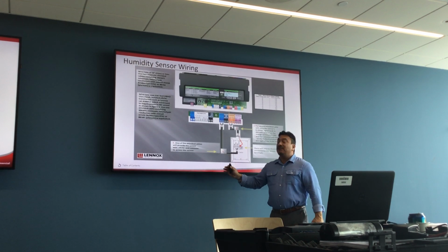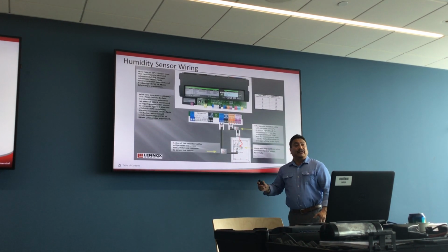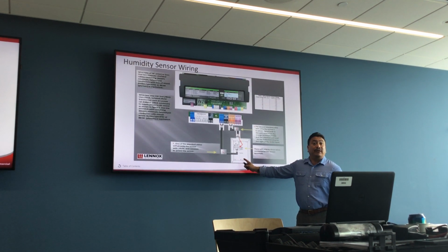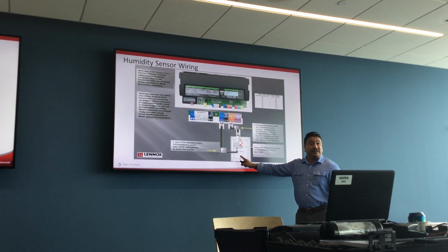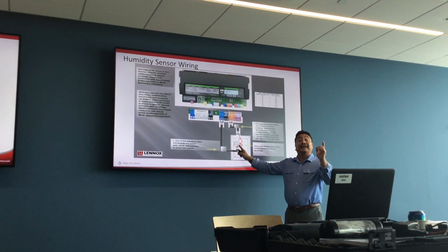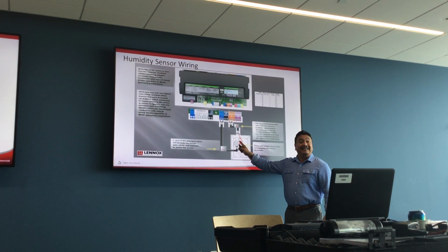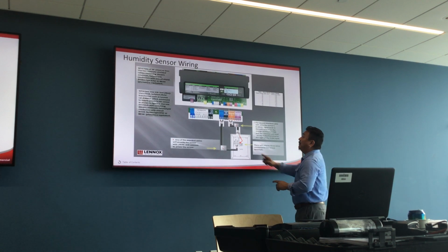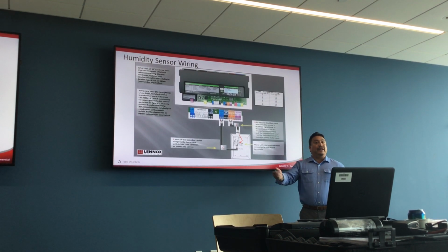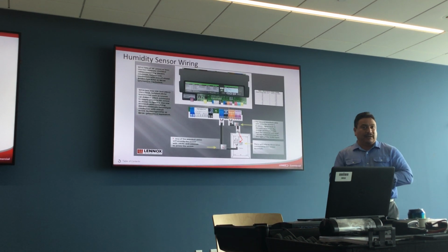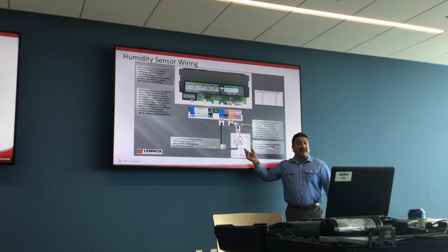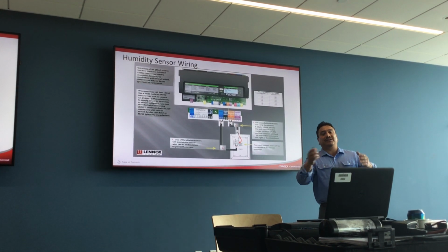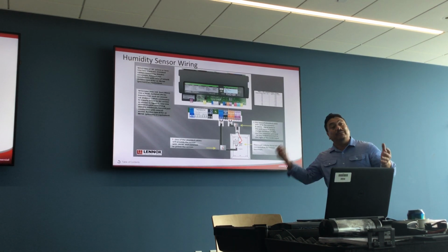All we're trying to impress upon you in this slide is the wiring arrangement for a humidistat, and where you would land it on the board. Because we're relying on an analog signal, we have to power up the sensor. Through rectification, we convert that 24-volt AC signal to a 0 to 10-volt DC signal, which translates as scale back to the unit. Depending on how you program the unit, that signal strength determines how often you will be utilizing Humiditrol. Or you may just have a set point built into the humidistat, and when you go over that set point, you send 10 volts DC. Boom. It all depends on how you set it up, and that's something Jeff would probably set up with you from the front end.